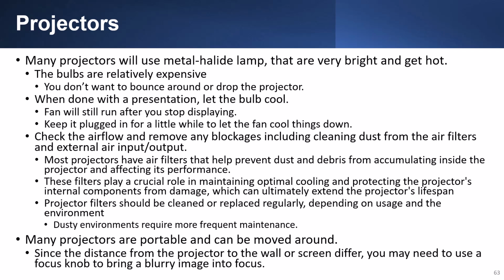Most projectors have air filters that help prevent dust and debris from accumulating inside the projector and affecting its performance. These filters play a crucial role in maintaining optimum cooling and protecting the projector's internal components from damage, which can ultimately extend the projector's lifespan. Projector filters should be cleaned or replaced regularly depending on usage and the environment. Dusty environments require more frequent maintenance.